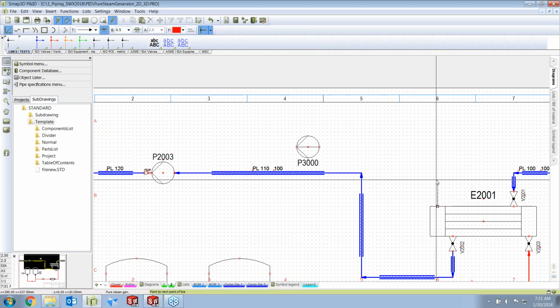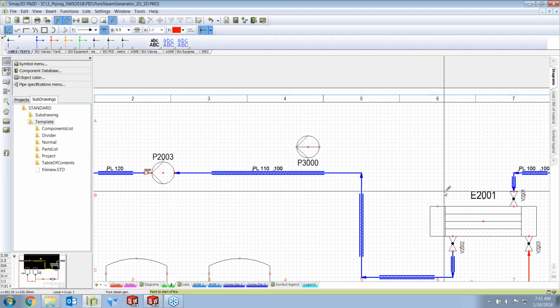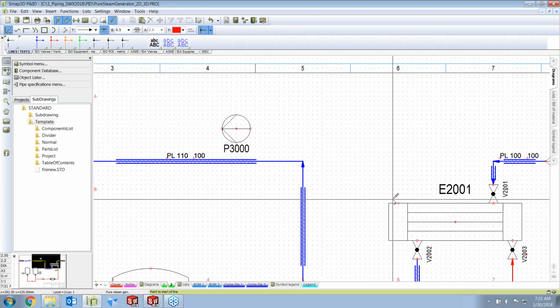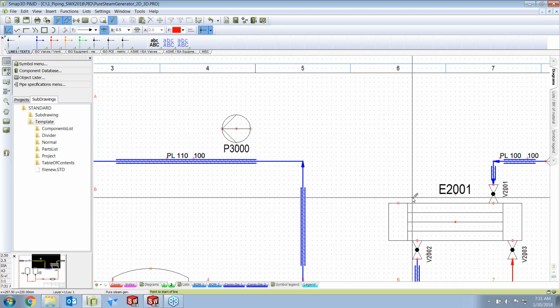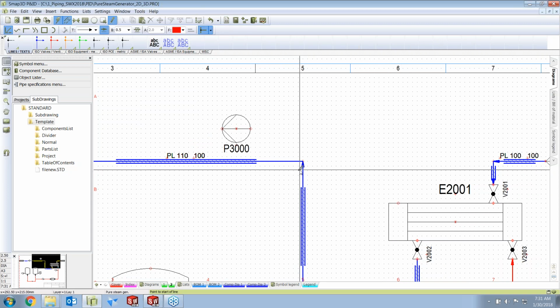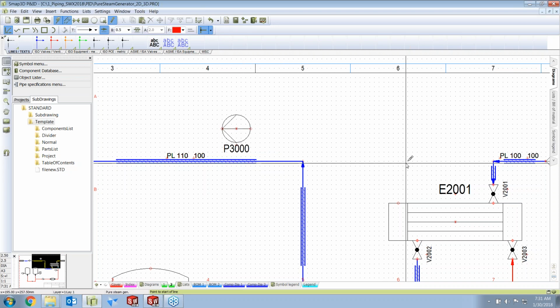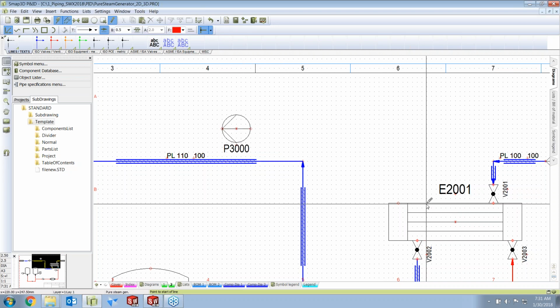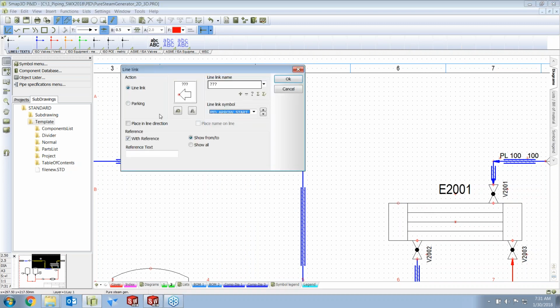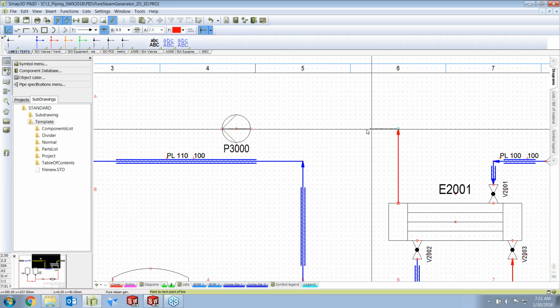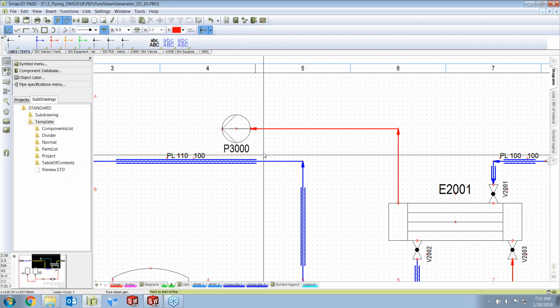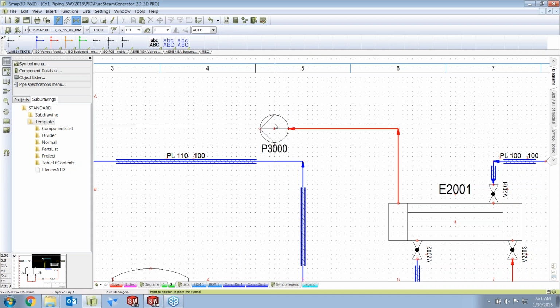Okay. And again, it's important also to know, back to that whole built for schematic capture, if we try to draw a pipeline that doesn't connect to something, notice these little red diamond shapes. These indicate connection points. If I try to draw a pipeline that's not on a connection point, it flags me and says, are you sure you want to put a piece of pipe out in the middle of nowhere? And I can park it there. In my case, I just mispicked, and so I can come back here, and once you actually do get it on a connection point, they connect and they stay connected.